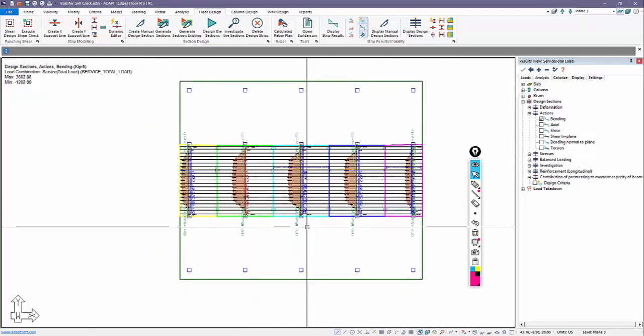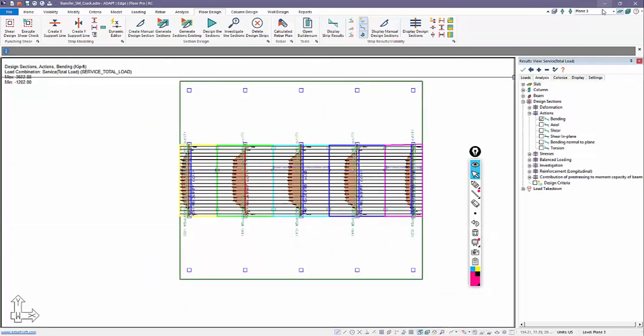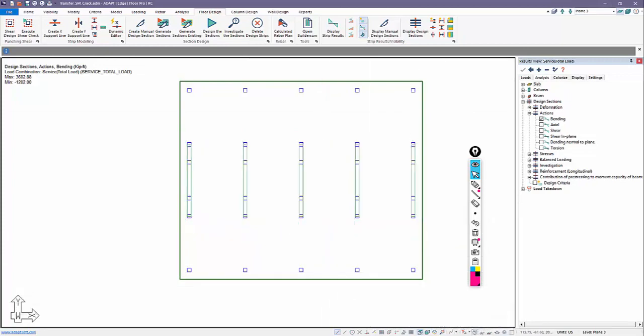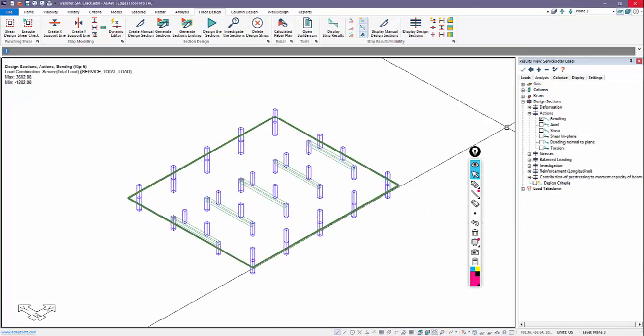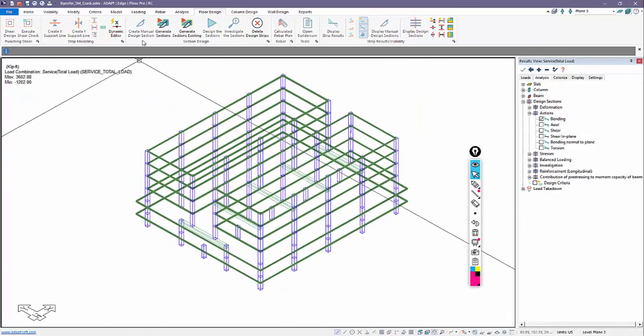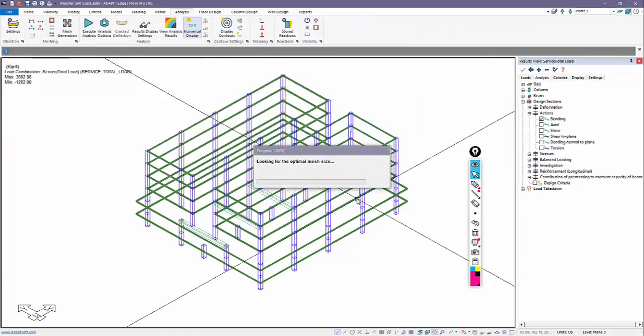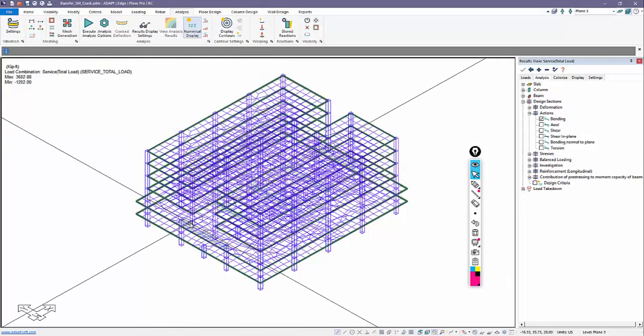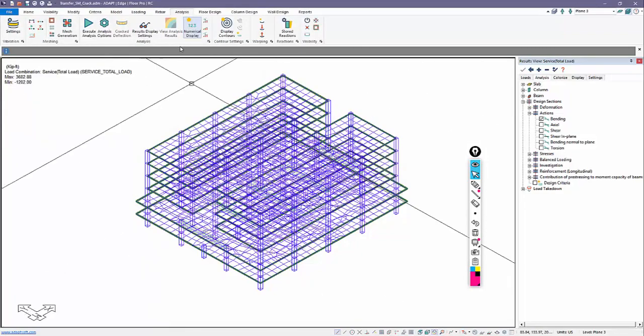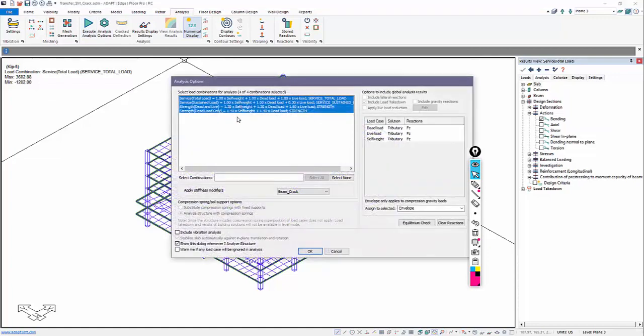The alternate way of doing this would be to obtain finite element reactions. So I'm going to back up and now go to multi-level mode, and I'm going to mesh the entire model because we want to obtain reactions in those columns, but we want to base the reaction now on finite elements. So we're going to execute the analysis for finite elements. Notice that this actually is inactive. This is grayed out. It doesn't apply to global run.